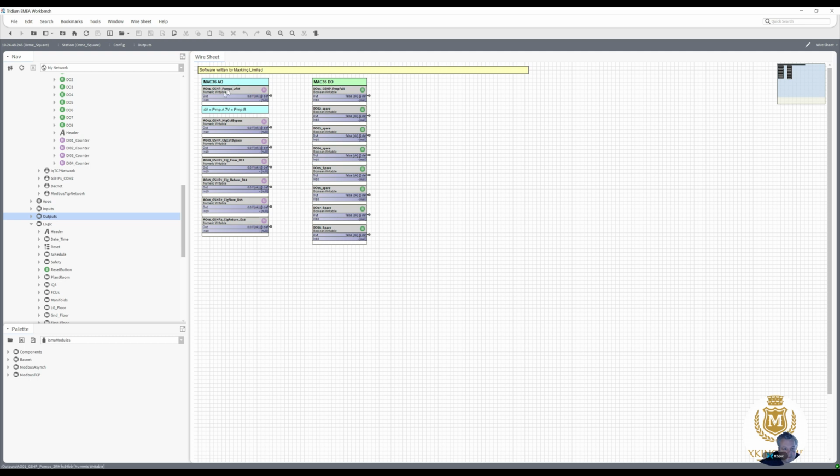Ground source heat pump 2RM module, and then 0 to 10 valve analog output 2, 0 to 10 volts for the heating, analog output 3 for the cooling, and then we've got ground source heat pump 1 cooling flow, D13, D14 on the trend for the return, and heat pump 2 D15 for the flow and D16 for the return.